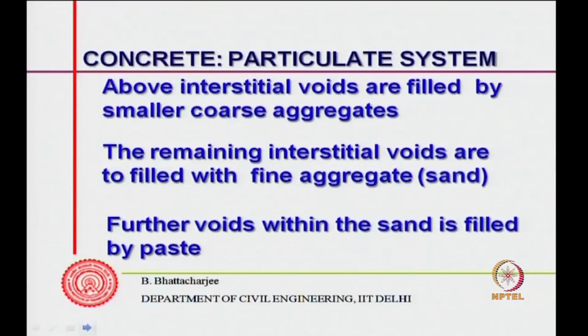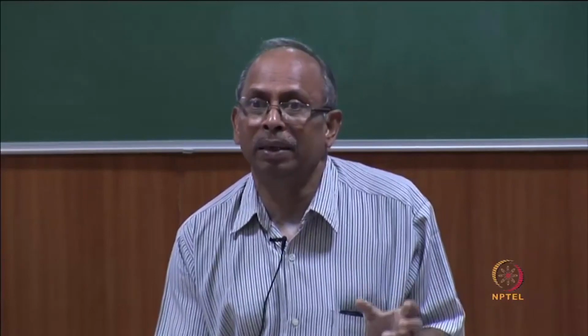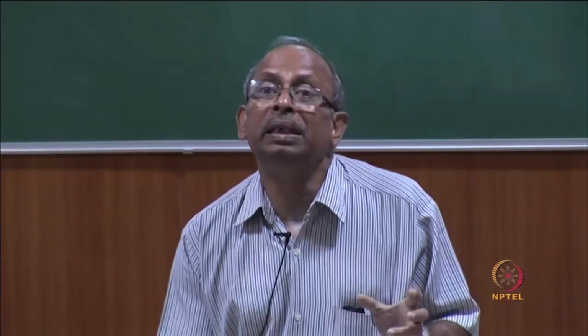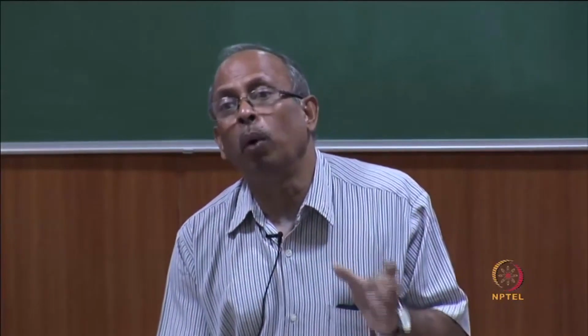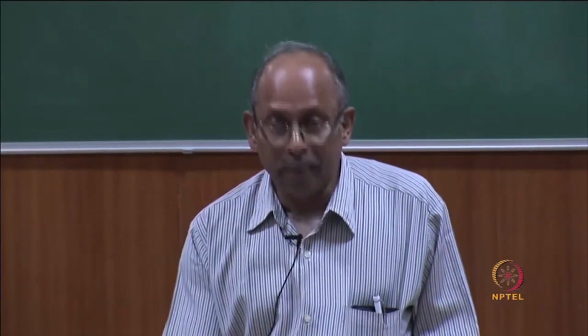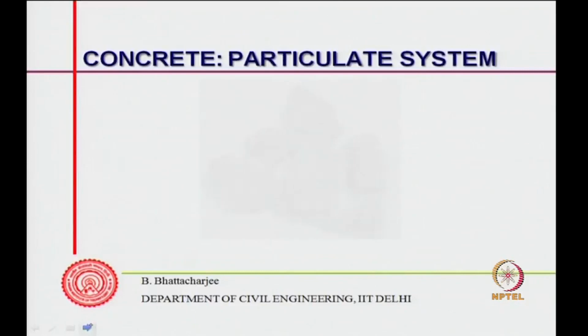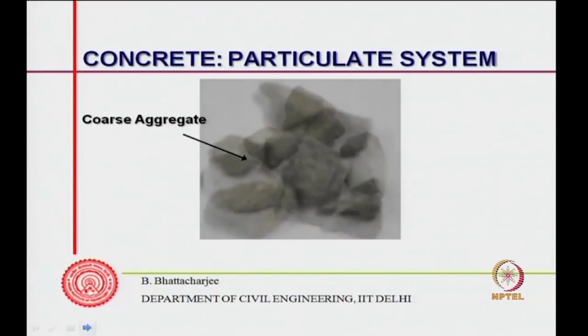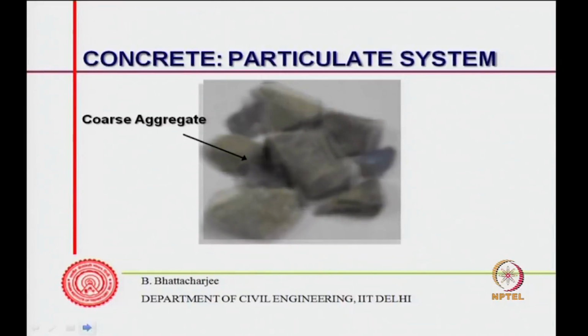Now, the further voids which are there within the sand are then filled by cement or cementitious paste or powder and water paste. So, that is what the concrete is, and if we look at it, for example, the same. So, this is your aggregate system, a few of them, let us say, and let us just arrange them in a slightly different manner. We get it, this is the coarse aggregate, they get arranged in this manner.